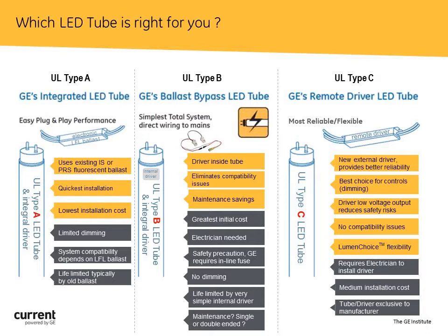And then finally, the other negative with Type C is that because the drivers are not standardized, once you buy a GE Type C driver, you're really going to have to stay with GE tubes. And likewise, if you buy somebody else's, you'll have to buy their tube. There's really no crossing of manufacturers with different manufacturers' drivers. Tubes and drivers are really dedicated right now. At some point, they will become more universal, but today you really are stuck with staying with a Type C tube and a Type C driver from a single manufacturer. That's it for this slide.